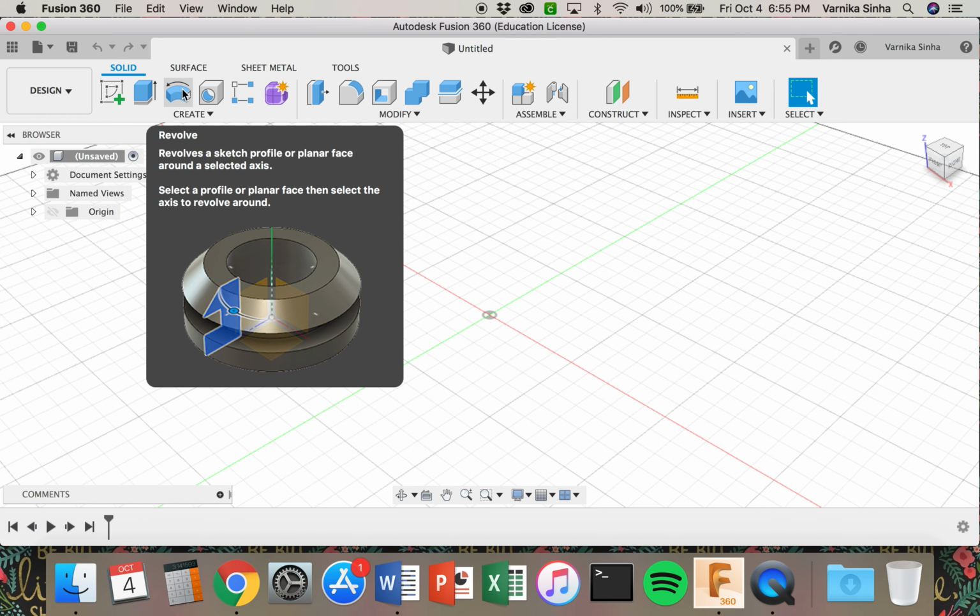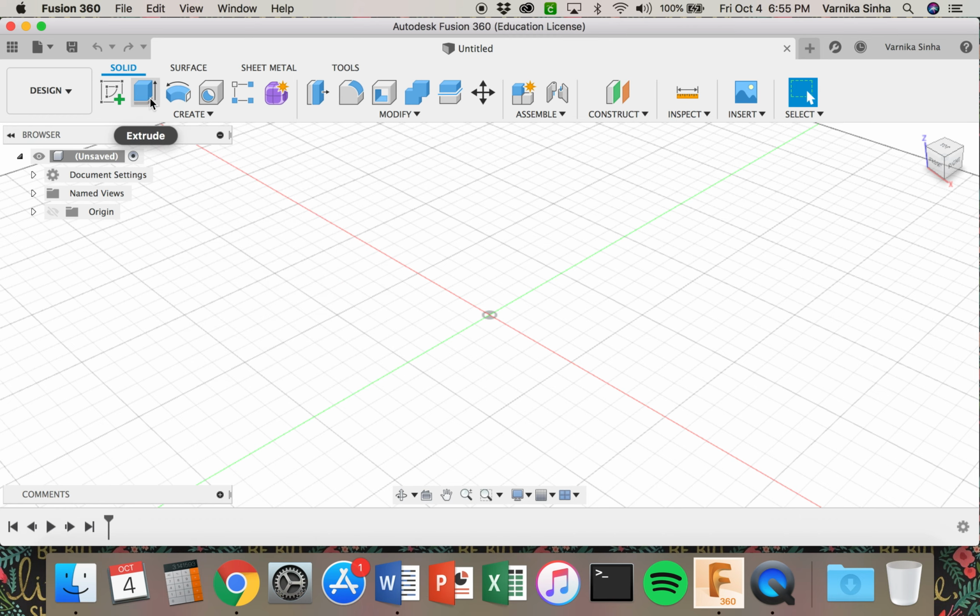So this is extrude. And then finally, we have revolve. As you can see, that blue highlighted shape is the sketch that we made in 2D, the 2D image of the object. And then we rotated it 360 degrees around the axis, which here is the green line, which formed this object. So this is revolve. Sometimes you don't want to extrude linearly, in one direction. You need to extrude in multiple directions. Well, revolve helps you with that. So those are the 3 basic functions we're going to go over in this video.